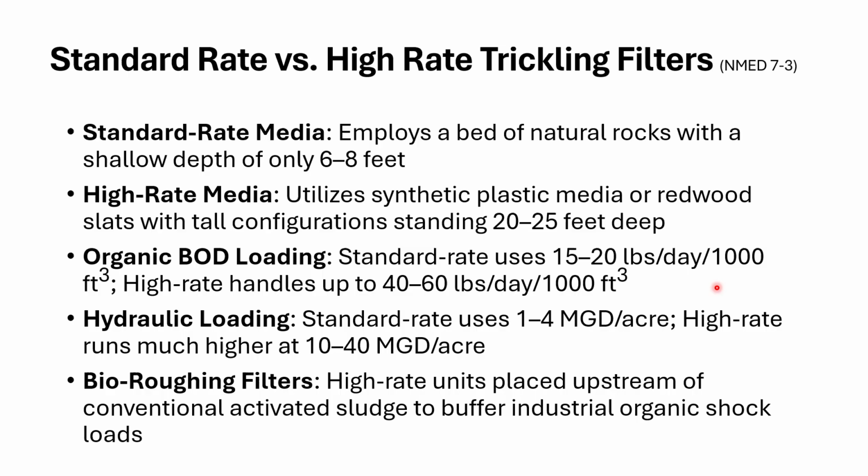For standard rates, it is going to treat 15 to 20 pounds of BOD. Should have put BOD in there, but I didn't. Pounds of BOD per day per 1,000 cubic feet. I think the last lecture I told you we use some funky units in wastewater and engineering. This is one of them. So we're looking at pounds of BOD per day treated per 1,000 cubic feet of wastewater. So it's 15 to 20 pounds of BOD per day per 1,000 cubic feet of wastewater.